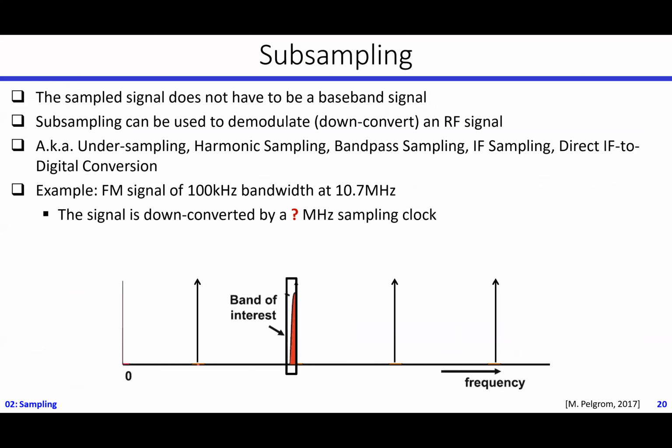Assume the reason that we would not be able to get the 1 megahertz signal is that it will overlap or mix the data, right? No, I'll be able to find it. If you did not know in advance that you are doing a subsampling process, your sampler will assume that your original signal is a 1 megahertz signal.